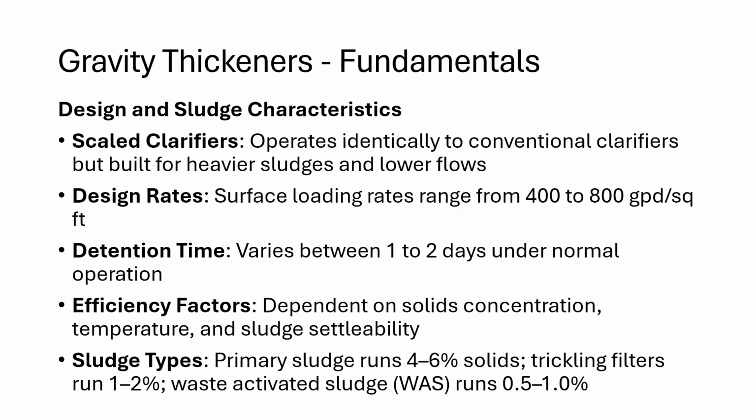So this leads us to what are called gravity thickeners. We can move our wastewater stream around as much as we like. We can use pumps. We can do a lot of different things, but we're basically imparting energy. We're paying for energy. But think about this: in a primary clarifier, we were basically letting gravity, a zero cost energy source for us, handle the separation of those suspended solids down in our waste stream to form that sludge blanket. We're letting gravity do the work for us. Same kind of thing in a sludge or a gravity thickener when we're dealing with sludge, okay?